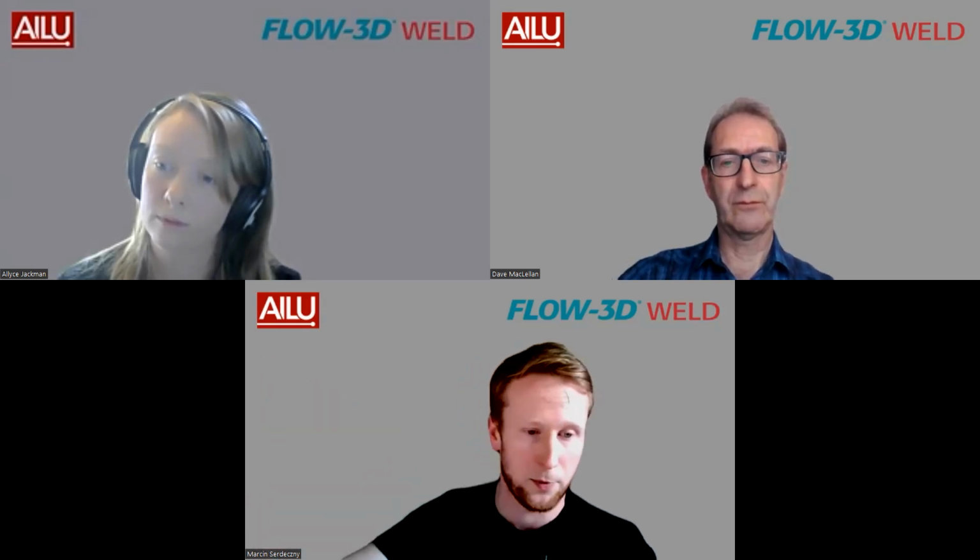Yeah, I've actually done a similar study as well. And I even coupled it to our other software, which is called Flow3dX, which is like an optimization algorithm. I was hoping to find the parameters that give you the same penetration, but for example, a lower mixing of, in this case, steel to aluminum. And then the optimizer did its job. It was trying to vary parameters as much as possible, but actually what you get is just a straight line. I mean, the more penetration you get, the more mixing there is. So it was very difficult to find a sweet spot of parameters that would give you a high penetration, but no mixing at all.